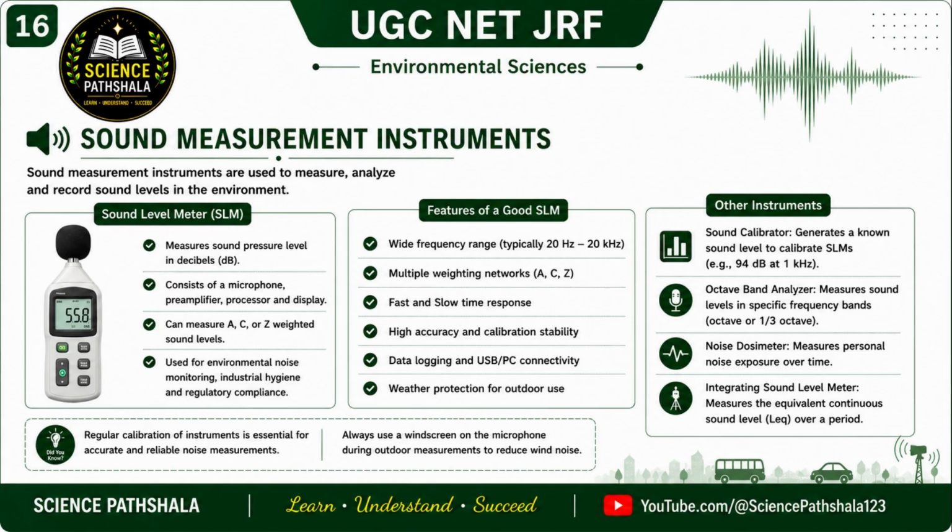Third is the noise dosimeter. A noise dosimeter measures personal noise exposure over a period of time and is commonly used in occupational health studies. Fourth is the integrating sound level meter. This instrument measures equivalent continuous noise level, also called LEQ, over a specific duration. Finally, always remember, regular calibration of instruments is essential for accurate and reliable noise measurements.